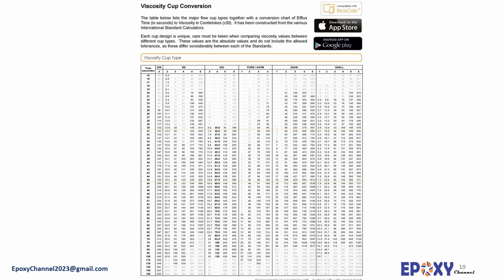There are also times that a customer knows the acceptable viscosity which works fine for his or her system, but in different units. You provide the TDS of your product to a customer in which the viscosity has been presented in, let's say, centistokes, for example, which is the standard way. He or she needs to know what that means in Ford cup viscosity, for example. You have to change this viscosity to the unit he needs.